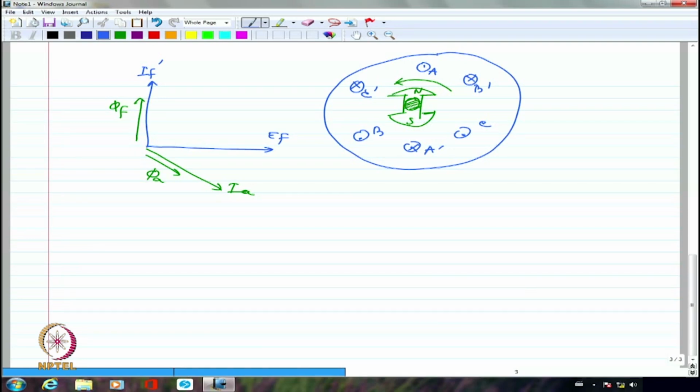There will be a voltage drop, definitely, the resistance will be there, but we are not unduly worried about it. If I have to calculate IF, VF is the DC voltage that I am applying, and RF is the field resistance. So I should say VF divided by RF will be IF, which is a steady state current. I am not going to have any transients because I have placed one particular voltage. I am not disturbing it. I am giving that excitation for quite some time. As simple as that. Right?